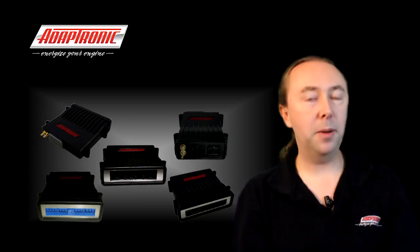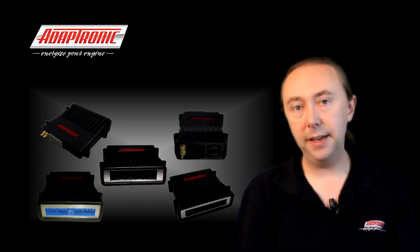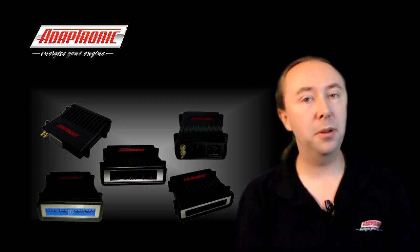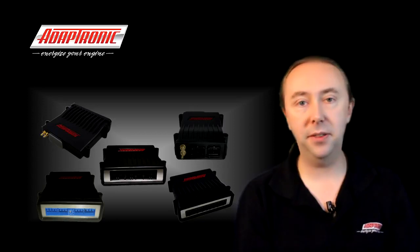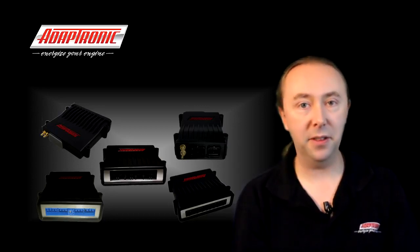Hi everyone, in this video we're going to talk about how to set up open loop boost control on the modular ECUs. Now in open loop mode, it means that the ECU has a duty cycle which it feeds to the solenoid valve, and whatever boost that generates is what you get. Now a lot of tuners like this because it's very simple to set up, but it does have its limitations, so let's talk about the physical hardware that we have to deal with first of all.